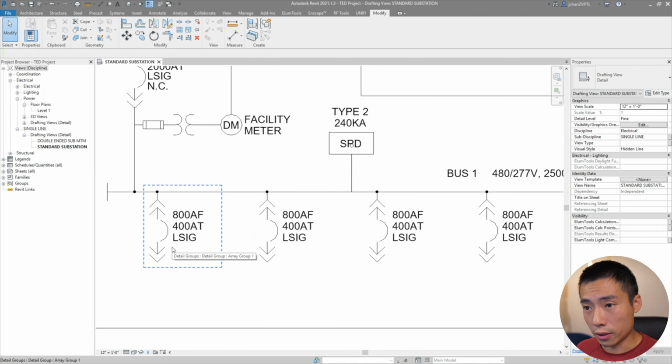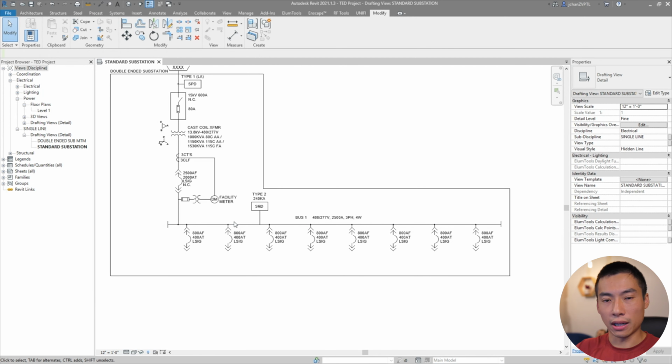So these draw out breakers are used to provide power to your switchboards, your eyeline panels, or your motor control centers. You would take substation power to something else that'll distribute it down to the panel or breaker size. Rarely do you ever put a piece of equipment directly onto a substation.